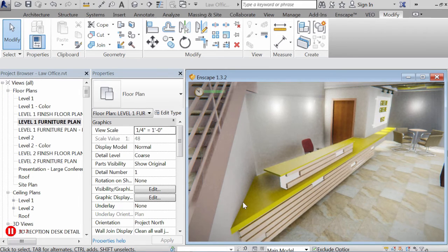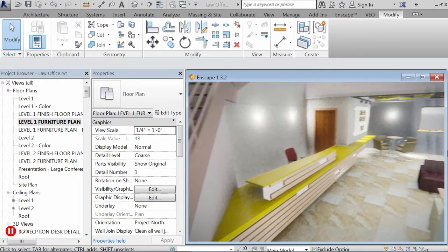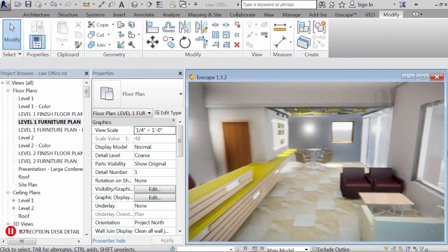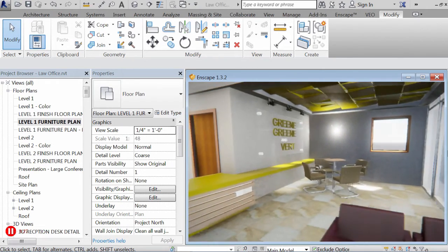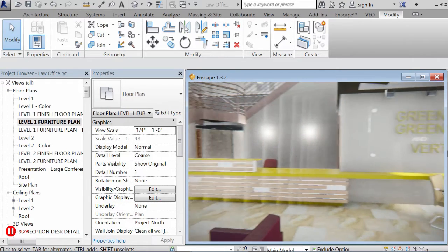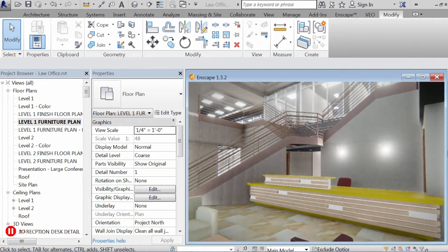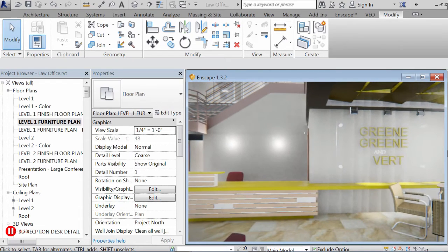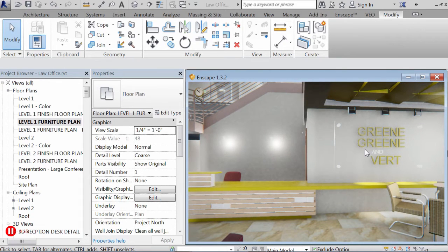Yep, it's in place because it's contextual in how it engages that angled stair, and then the wall beyond on the right. So that's an in-place family with specific materials applied to it, and there's an in-place sign that you see to the right. Where the letters are. Yep, kind of on a piece of Perspex, like it's pulled out from the wall.